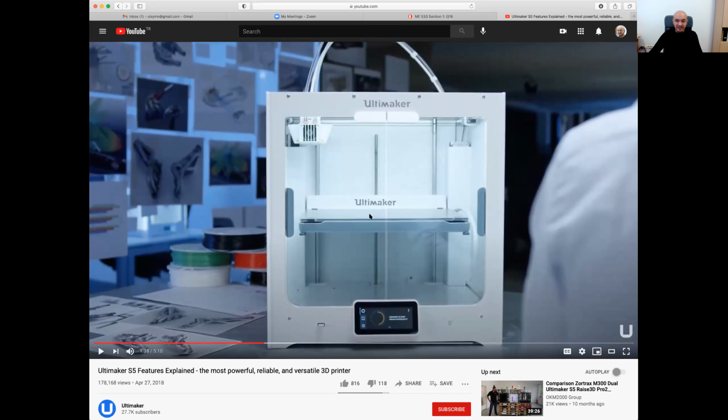So this is the first actually level which your product is to be printed, and its level is highly important. It should be perfectly leveled, otherwise you'll have problems during your print, and that's why this machine is going to level it by using some capacitive type of sensors in its head.